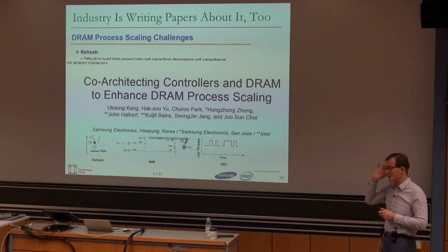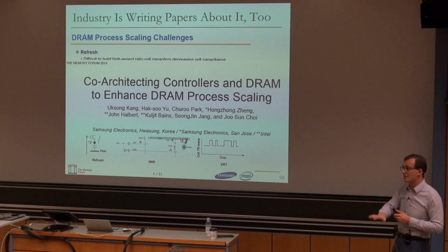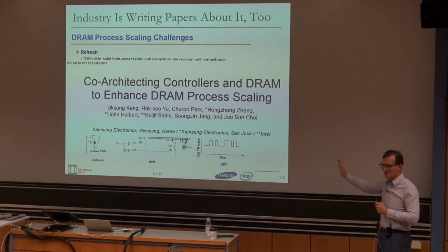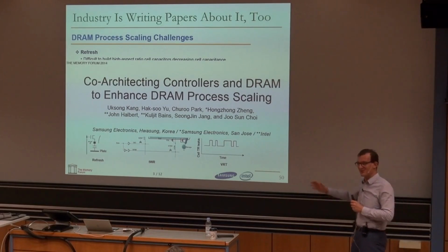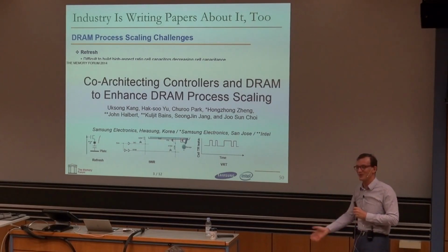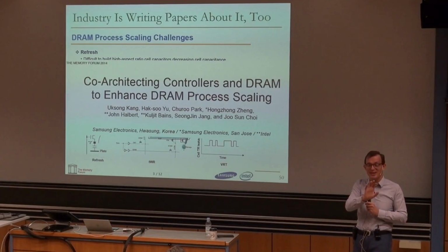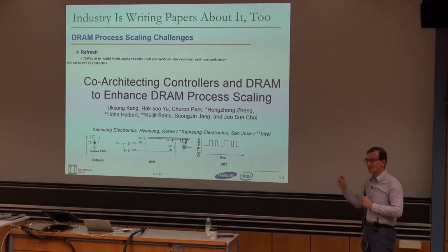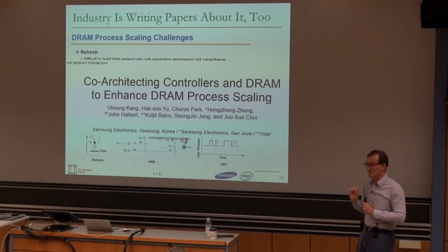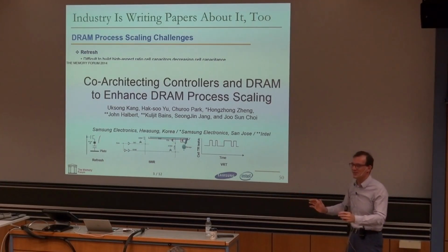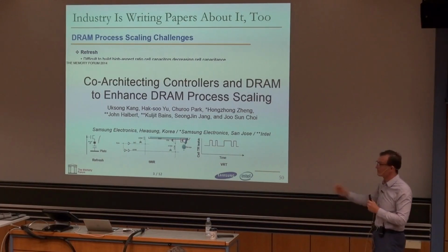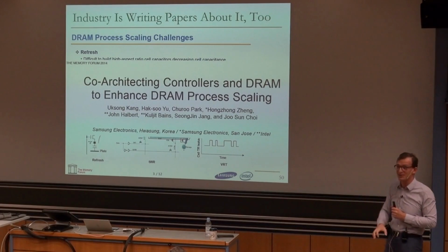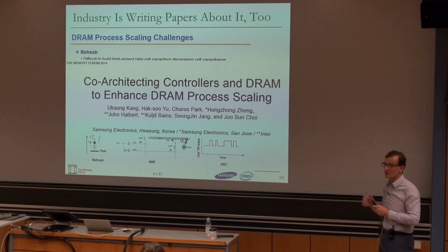But if you went to DRAM manufacturers about 10 years ago or even 5 years ago, well, I guess 5 years already passed since this paper, so things are going fast. I guess I'm getting older. But if we went to them 10 years ago and said, I want ECC, error correcting code, in your memory, they would kick you out of the room because they care so much about capacity. But now the mindset is changing because there are other problems that are really driving things. Reliability is a huge issue. As a result, now they have error correcting codes inside the main memory.